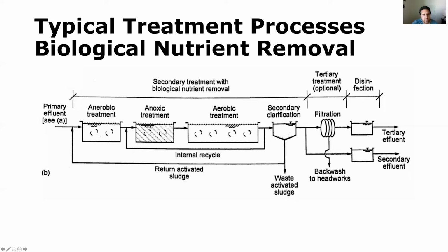An important constituent that needs to be present for denitrification is an organic material, right? Those microorganisms are using the nitrate as their oxygen source, but they are degrading some organic molecule. So either that organic compound has to be added back into the wastewater, or if you have this internal recycle, the organic matter in the wastewater itself can serve as that energy source for those microorganisms which are denitrifying.